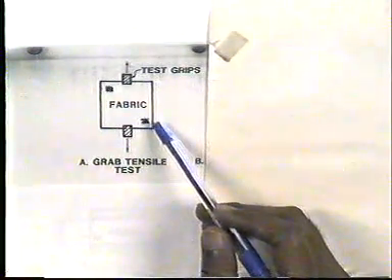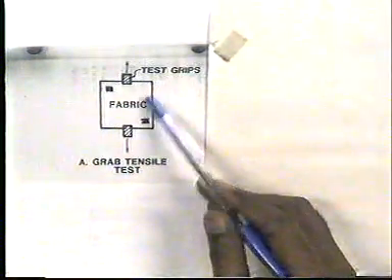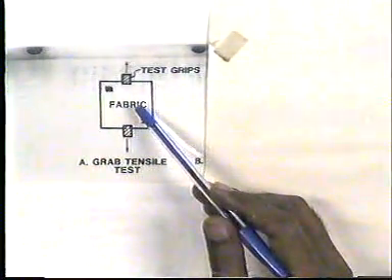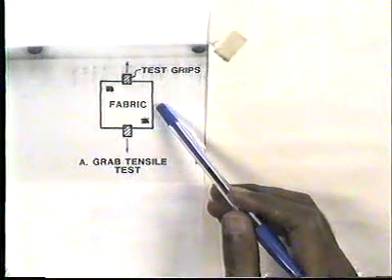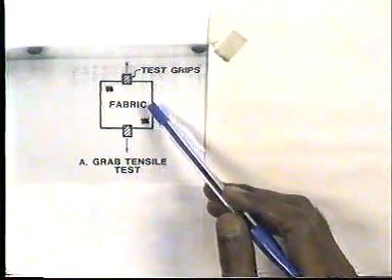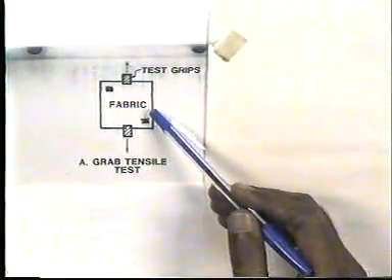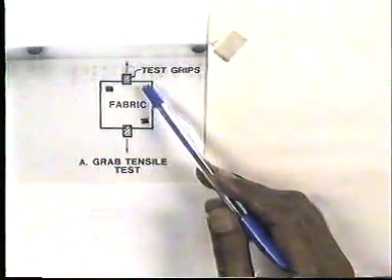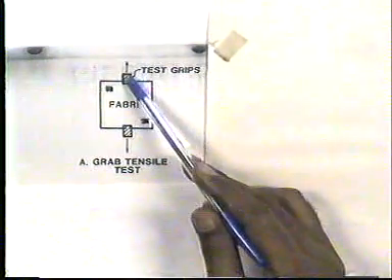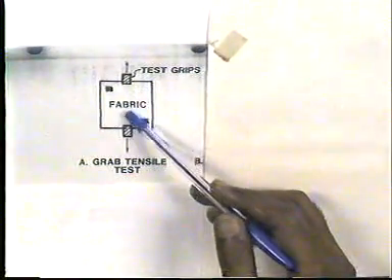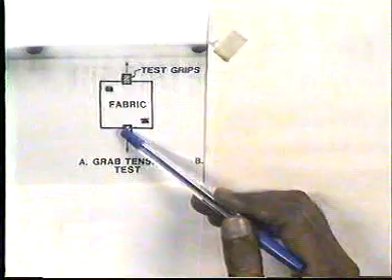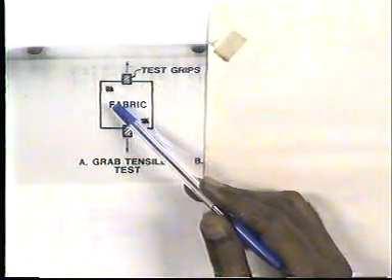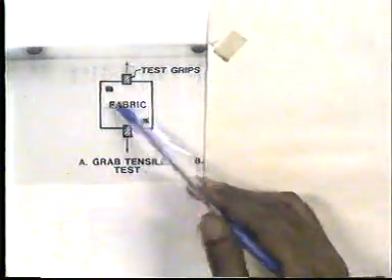Here, as the width of the tested sample increases, the tensile value increases, since the contact length between the individual fibers is much better at greater sample width.